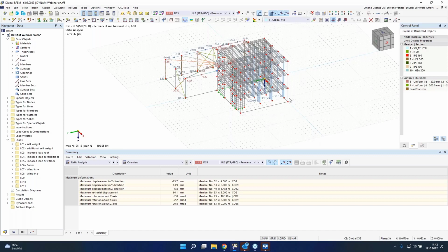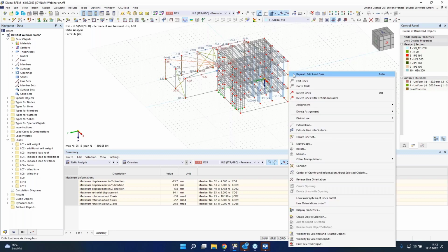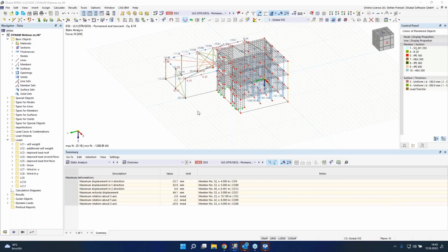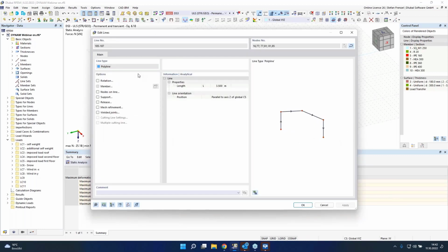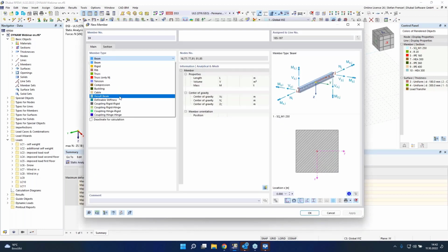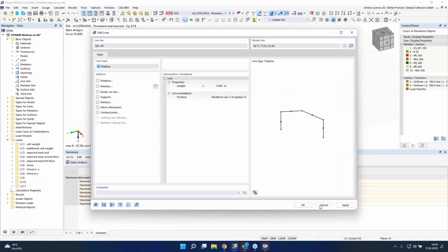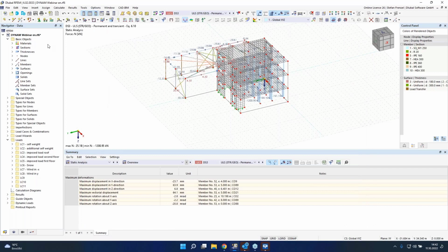That means I have to create a beam. That's added lines, and here I'm able to create a member, and also say, okay, a result beam. Here I can integrate all surfaces and all members of the structure to member internal forces. Then I can compare the shear force of this member with these two result combinations or design situations. But in our case today, we want to do it in a little bit other way.